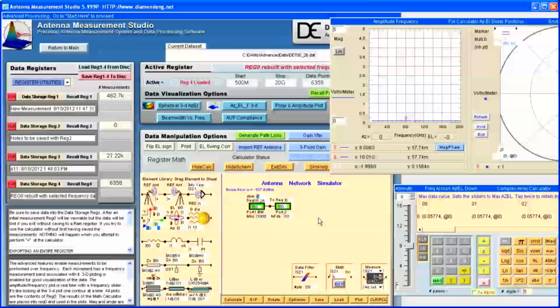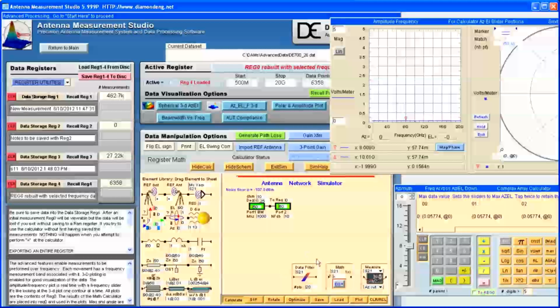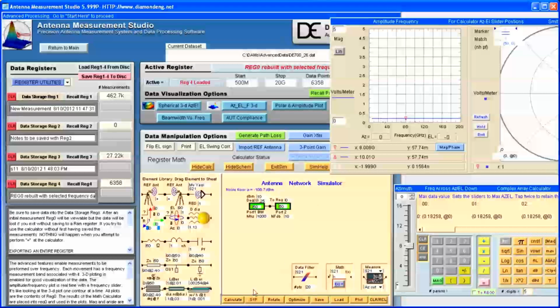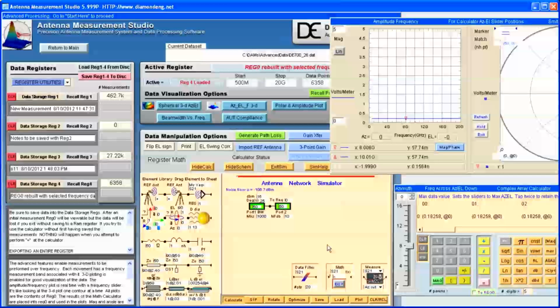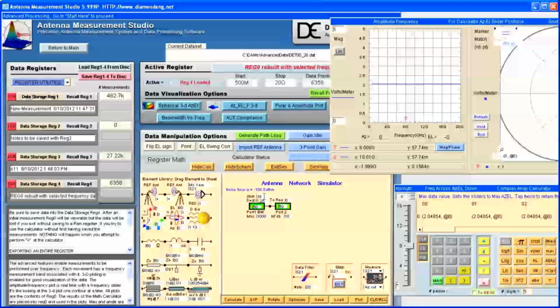We'll first set the power to plus 10 dBm and recalculate the volts per meter. Now we're going to try and change the power level to plus 16 dBm, and again we recalculate the data. Now we have a very small voltage. If we now increase the power level to 1 watt, plus 31 dBm, we can see we are very close to 2 volts per meter.